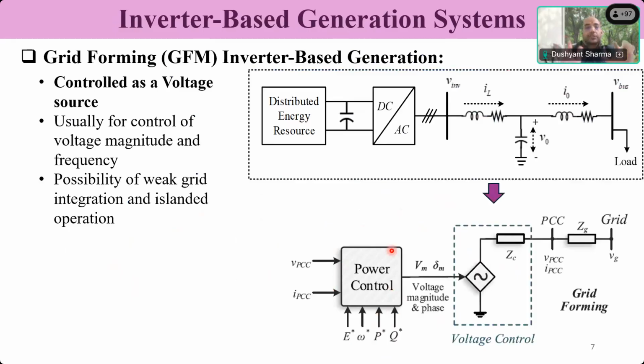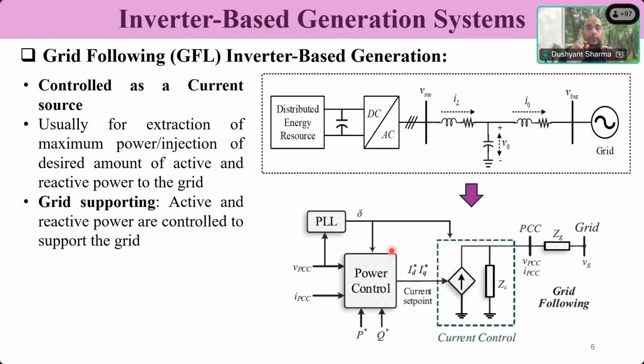So in summary, the point is we have an inverter, which is a grid following inverter, connected to the point of common coupling. It has to be controlled to get the desired P and Q. That is done with the help of a controller. The controller controls the current that is injected by first taking the voltage reference of the grid, knowing the angle of the grid voltage, and then the current angle is accordingly adjusted, lagging, leading, or in phase, to inject the P and Q. That is the overall philosophy of a grid following inverter.